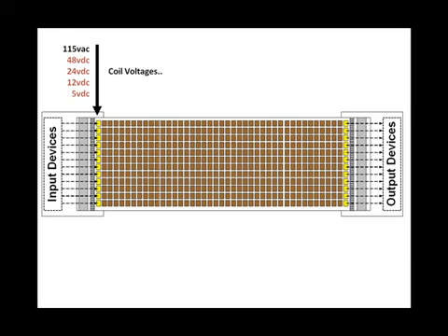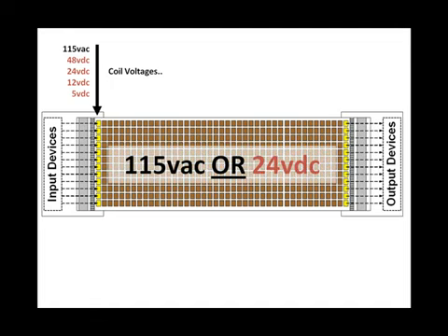The vertical column of yellow relays on the right will have the same coil voltage as the brown relays on the control panel, either 115 volts AC or 24 volts DC. However, their contacts will be capable of handling whatever is needed in amperage for the output devices, as well as they will be switching whatever voltage is required by the output device.